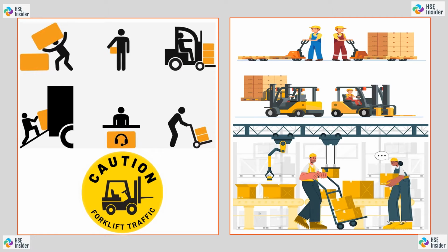Pallet jack and hand truck use. Ensure the load is evenly distributed and never overload the equipment. For cranes and hoists, inspect cables and rigging before use and never exceed the safe working load.